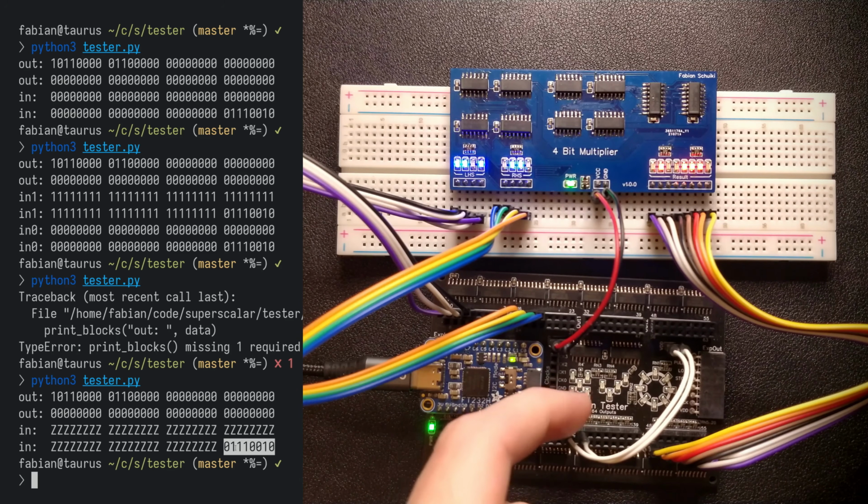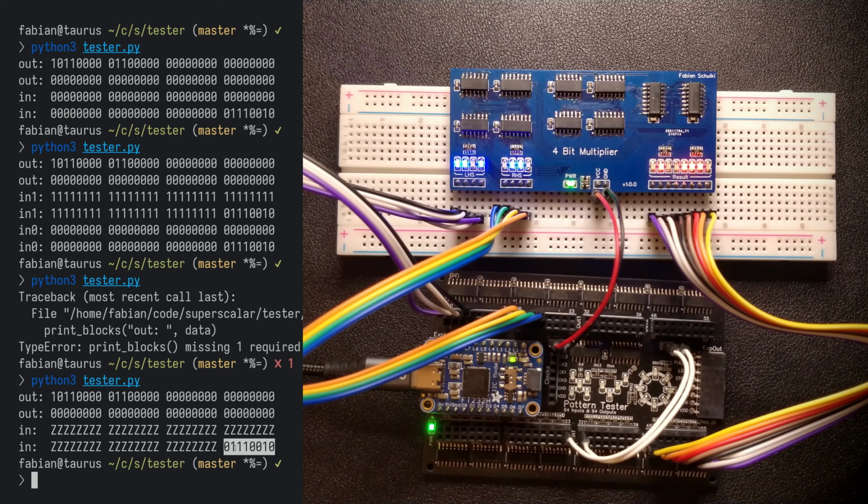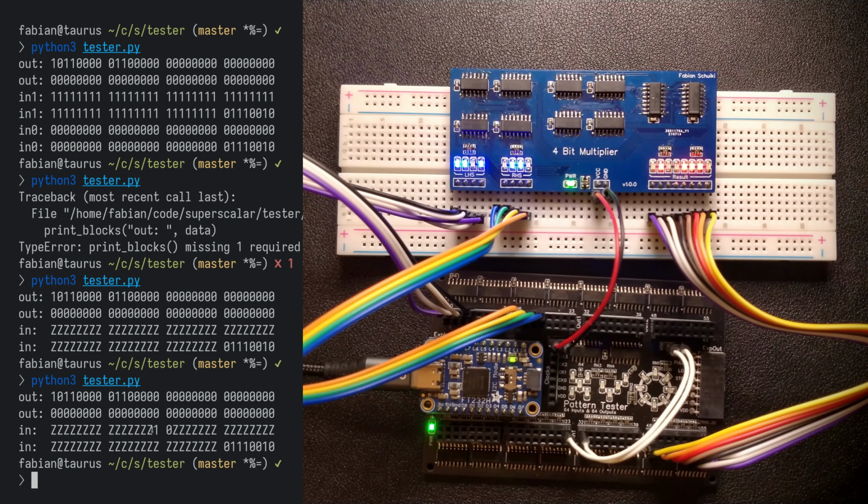And so I connected 2 jumper wires here to VDD and ground. These are going to be these 2 bits here. So let's rerun this command. And as you can see now, these bits show up as strongly driven, as connected, because they're tied to VDD and ground directly. So this is going to make testing and working with the tester pretty convenient, because we can actually see if something is disconnected.